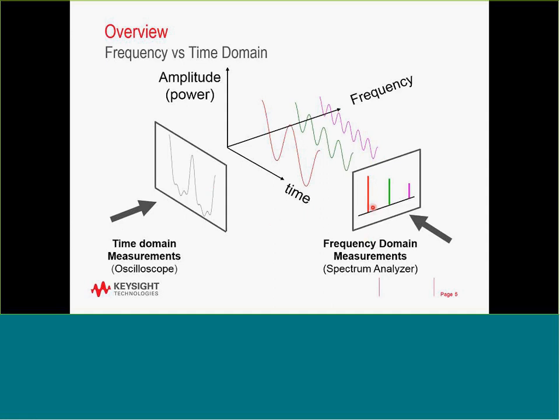It allows you to decompose the time domain signal into its frequency components. Sometimes it's useful. The time signal in the oscilloscope might look like a perfect sine wave, because the dynamic range of the oscilloscope, which is 8-bit, only provides something like 50 dB of dynamic range, and you won't be able to see harmonics.